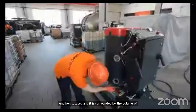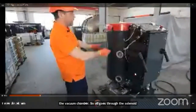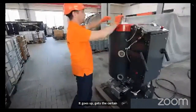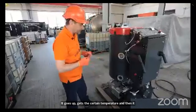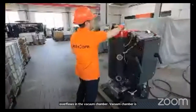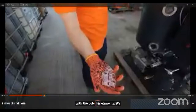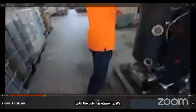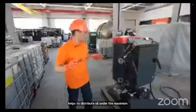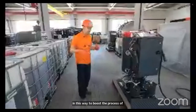So, oil goes through the solenoid valve into the heating area. It goes up, gets a certain temperature, and then it overflows into the vacuum chamber. The vacuum chamber is filled with polymer elements with extended surface. So it helps to distribute oil onto the maximal surface, and in this way to boost the process of evaporation and degassing.